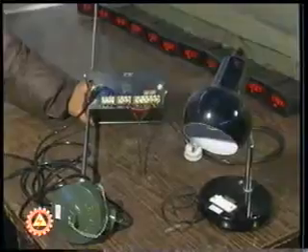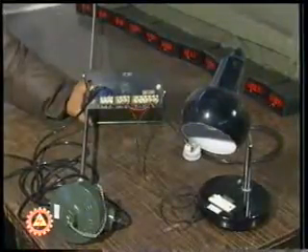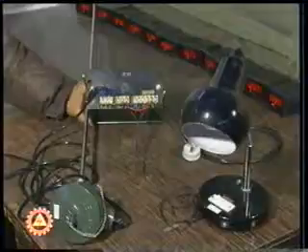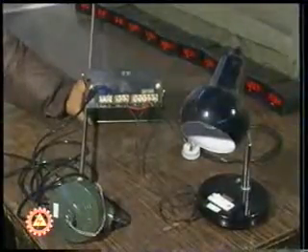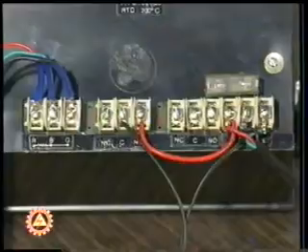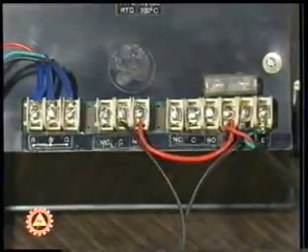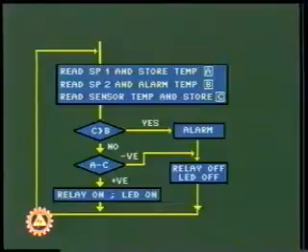The required gain depends on the total dynamic range of the input signal. Depending on the maximum and minimum temperature of the input, we may need a 10 or 12-bit AD converter. The corresponding software flowchart would appear in this way. After linearizing the input from the thermocouple, the system makes a comparison between the set temperature and the thermocouple output. If the process temperature is more than the set value, the relay is switched off.